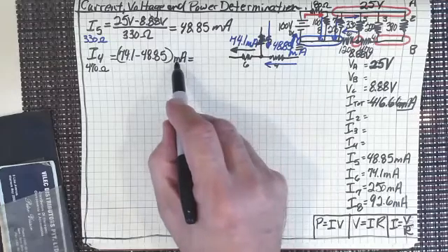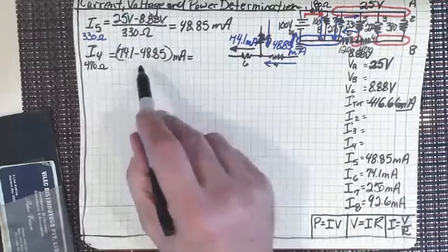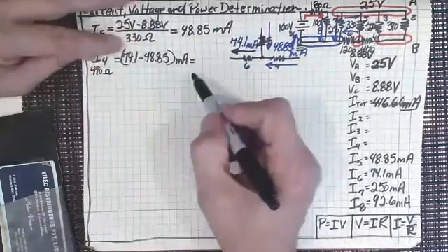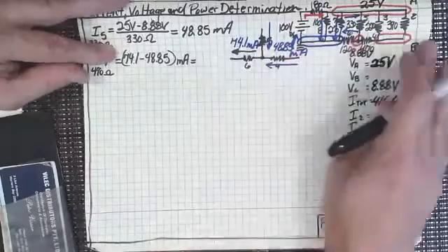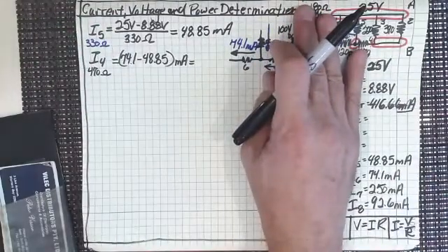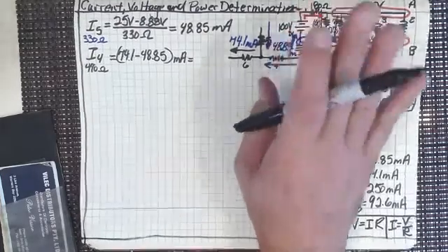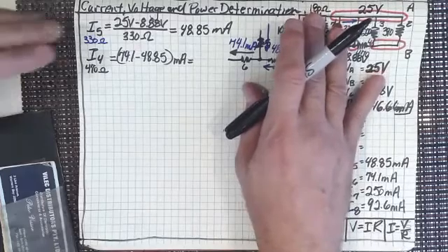Because here you've always got to use that times 10 to the minus 3, and you've got to put it in there. A lot of people don't. They just multiply it through by milliamps and think, oh, later on I'll divide by 1,000 or whatever. And in fact, they end up dividing where it should be multiplying and multiplying where they should be dividing, and the spaceship goes off into nowhere land.